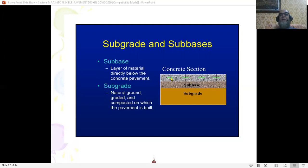So this is the dowel. These are the joints between the pavement. I have discussed that for JPCP, the joint spacing is around 15 to 30 feet. And for CRCP, we don't have these joints. Now, this subgrade is a compacted subgrade, and we will take its value in terms of K.